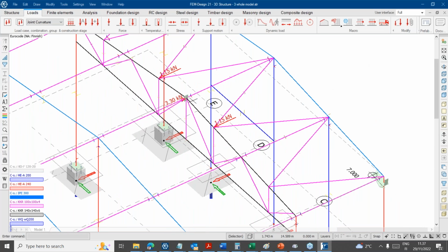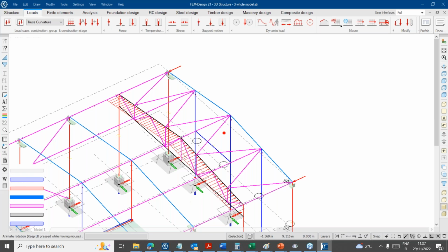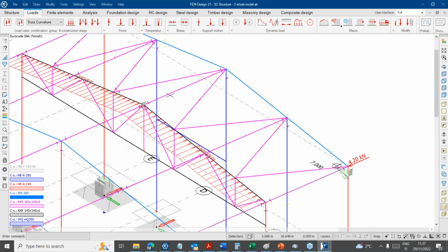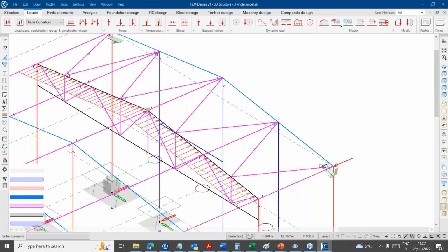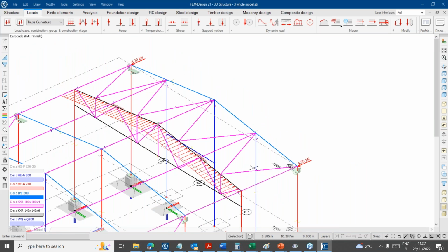If you do these eccentricities with the loads, the good thing is you can also reverse them really easily in the load combinations. So that's why they are so practical. And this is the last example. If this truss wouldn't be perfectly straight, you have to put this QD load there. And then you calculate the deviations of the trusses or these bracings, taking into account also the connection stiffness, and then you calculate the total QD, and then you have done your iterations and get the final QD. And of course, here you also have to take into account the wind load affecting at the same time.